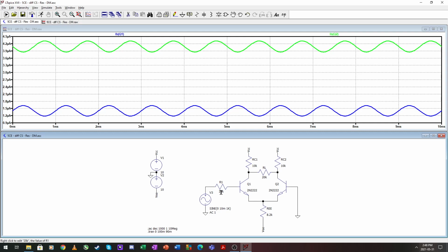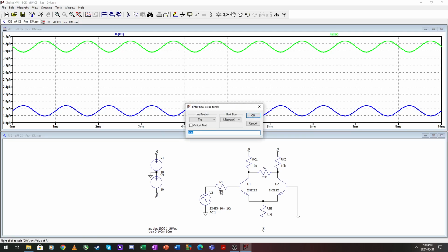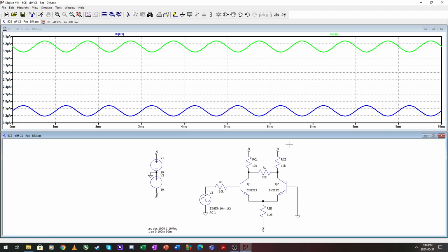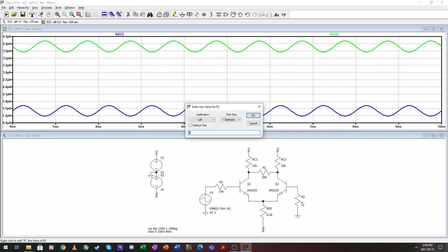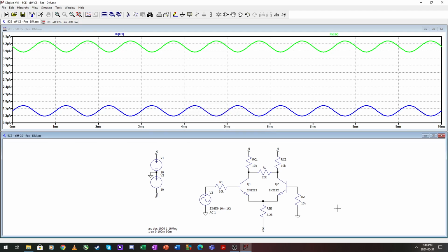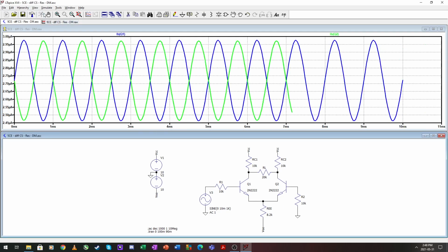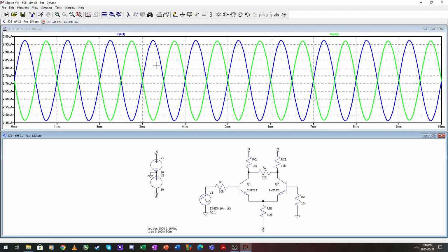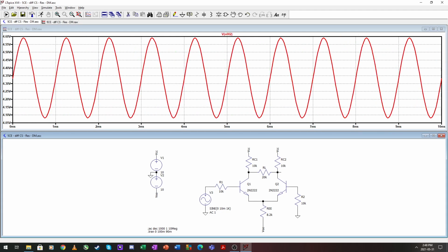We will get some offsets with it. So if you want to place a resistor here, it is best to split the resistor between the two inputs like that to have some form of balance. There the two currents will be falling on top of one another.